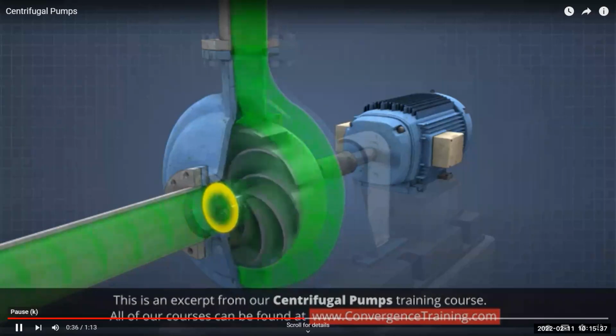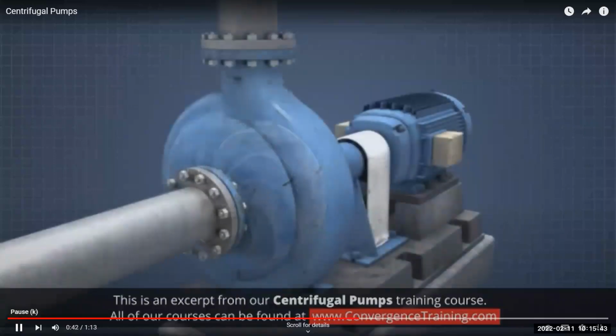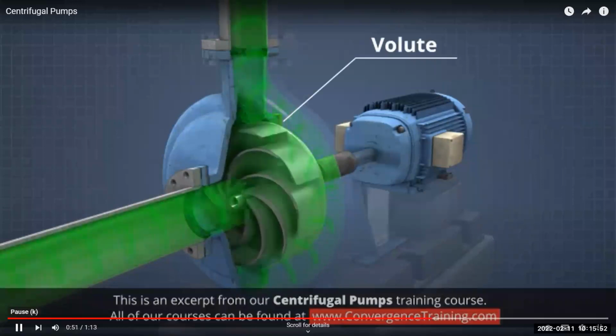Liquid flows into the pump through the suction inlet. Vanes on the impeller help direct the liquid to the outer edge of the impeller and into a gradually expanding channel called the volute, which collects the liquid and directs it to the discharge port.